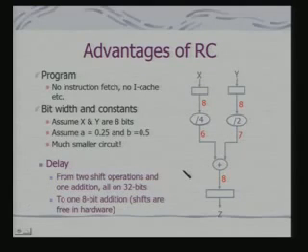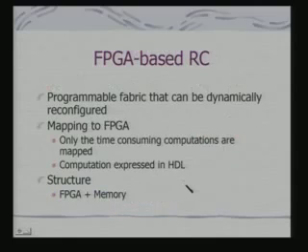The delay from 2 shift operations and 1 addition, all on 32 bits, is what happens when we use instructions, translating that operation into a set of instructions, compared to this kind of circuit. So what we have got is a 1-bit addition, and shifts are almost free in hardware, because if I am using a barrel shifter kind of circuit, building small such circuits using FPGA blocks, then I can do shifts in almost no time.